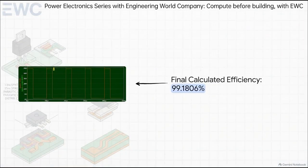Pulling back out to our macro view, let's check the final tally. Using those QSPICE .measure directives we established earlier, the software has integrated all those 13 nanosecond and 25 nanosecond power spikes across our entire simulation. The final calculated efficiency gives us a result of 99.1806%. If you look really closely at this graph, you can actually spot the slight difference between the green line, the power generated by the source, and the orange line, the power dissipated by the load. That tiny little gap represents the power lost purely during switching.